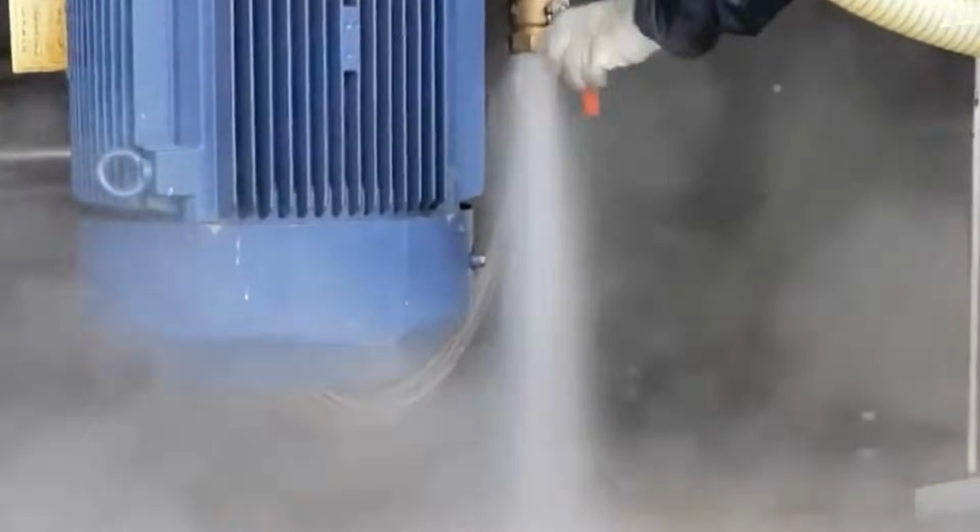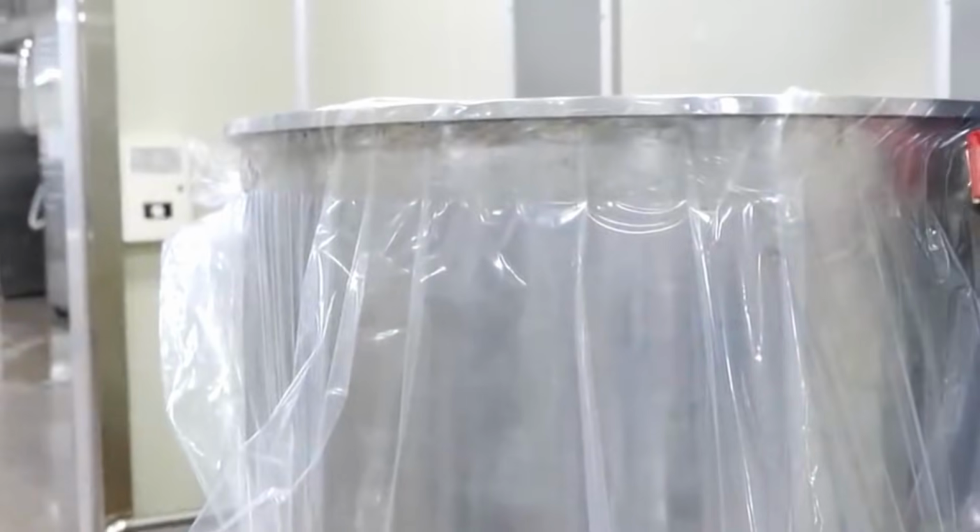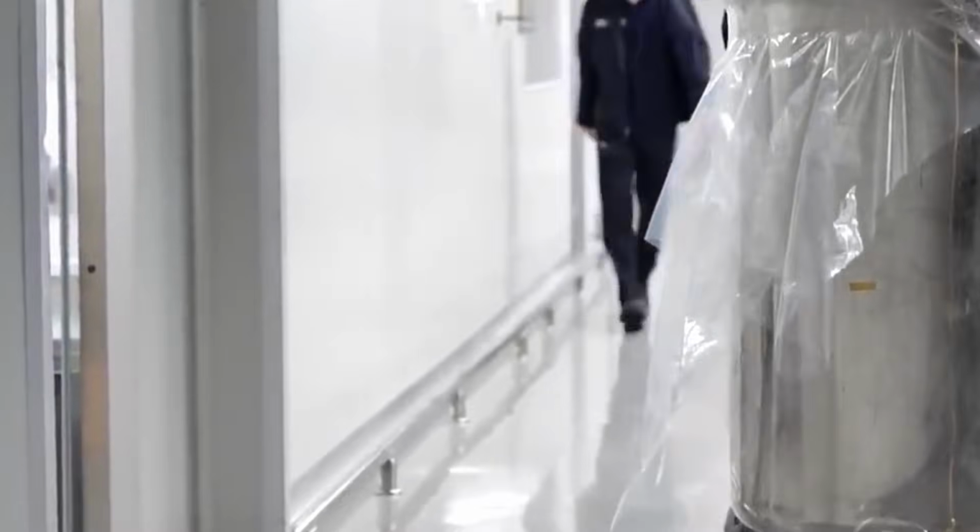The finished shampoo is then pumped through sanitary pipelines to the filling area. Transfer pumps are selected based on product viscosity and shear sensitivity, commonly using lobe pumps or progressive cavity pumps. Flow rates are synchronized with filling line demand to maintain steady supply.